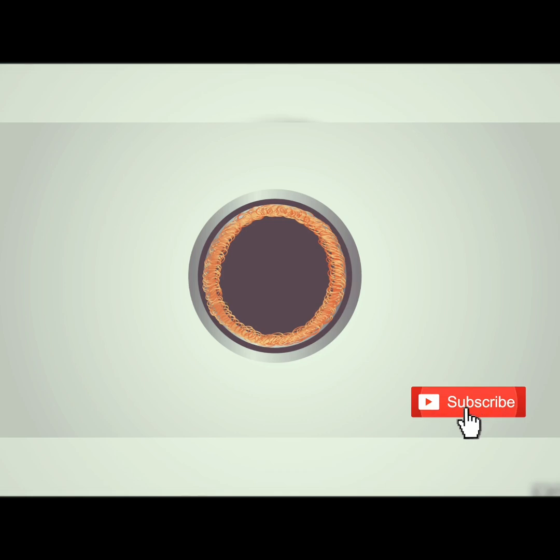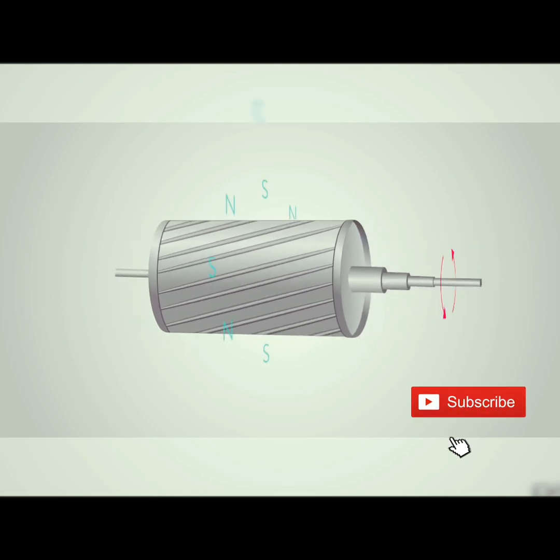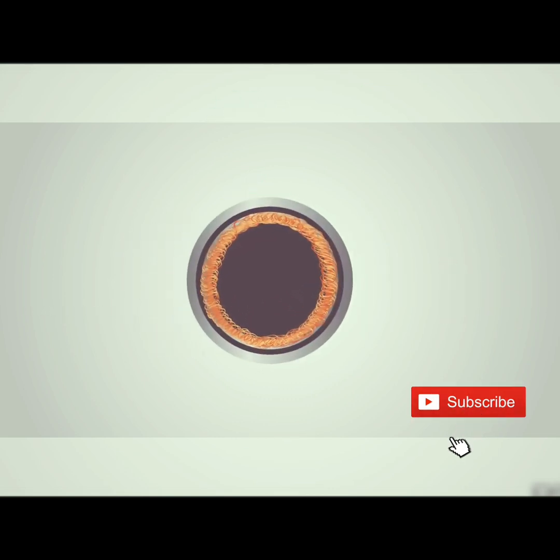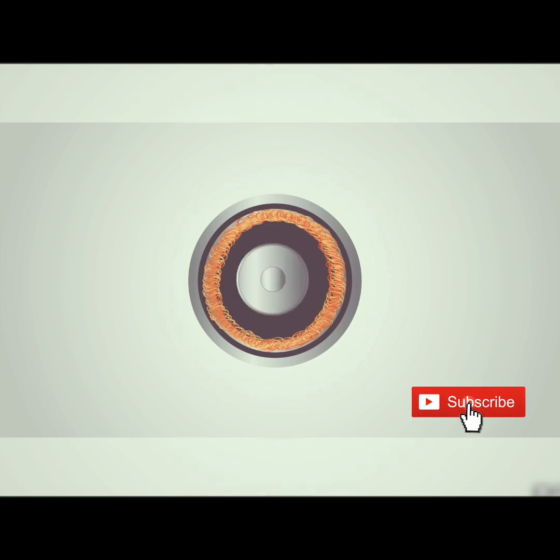The asynchronous or induction AC servo motor stator consists of stator core, armature winding, and lead wire, and the rotor consists of shaft and the rotor core winding. Most induction motors contain a rotational element, the rotor or squirrel cage. Only the stator winding is fed with an AC supply. An alternating flux field is produced around the stator winding with the AC supply. This alternating flux field revolves with synchronous speed. The revolving flux is called a rotating magnetic field, or RMF.